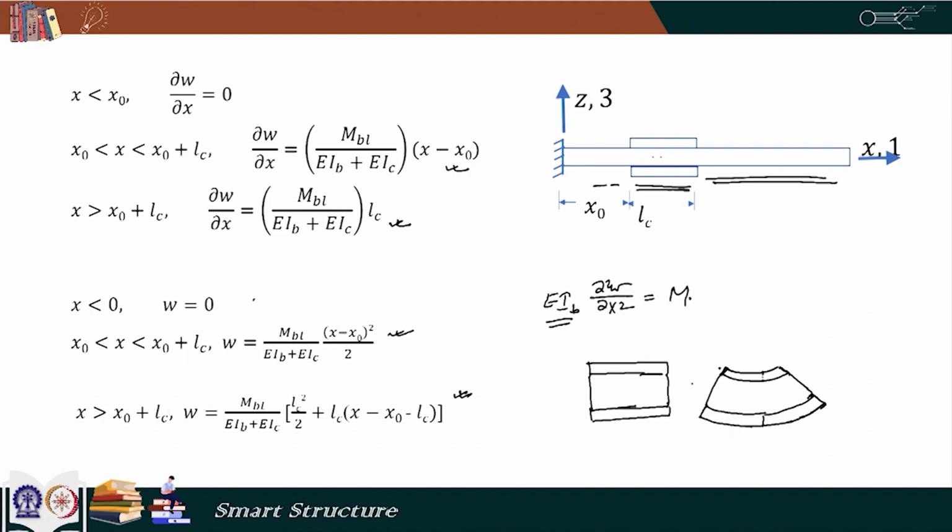And in fact, if we want to make our piezo behave in such a way that its strain is same, that is not very much feasible physically. So, that is a big assumption in the block force based method, and that is why the result, although the result was same in extension, because in extension or contraction it does not matter, this kind of bending does not come into picture, but in bending case the results are different.